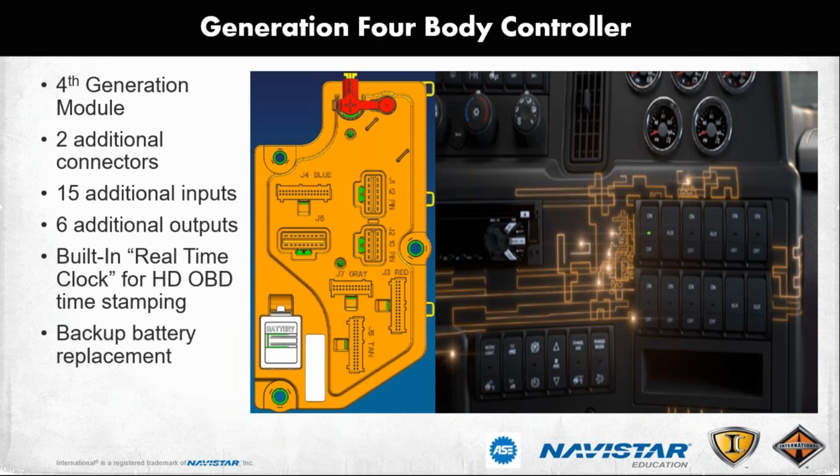All right, the switches in the dash, when the driver reaches up and pushes one of these, is actually an actuator. It's not really a switch. On the back side of this, this actuator is going to depress micro switches on the circuit board that is part of this switch pack module.